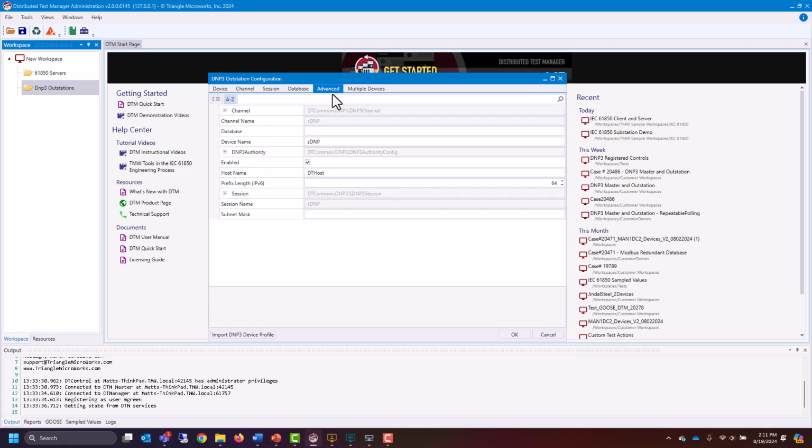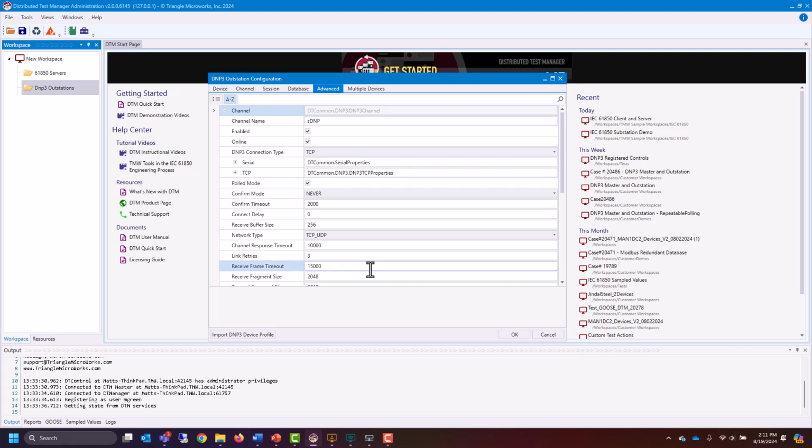The Advanced tab is where you'll find everything you did not find in the previous 4 tabs. The previous 4 tabs will get you done 80% of the time, maybe 90%. When you're looking for something specific, such as timeouts or buffer sizes or things along those lines, if you're getting a warning in the protocol analyzer that's mentioning a misconfiguration, you might want to come in here and check to make sure that these are the appropriate and expected values.